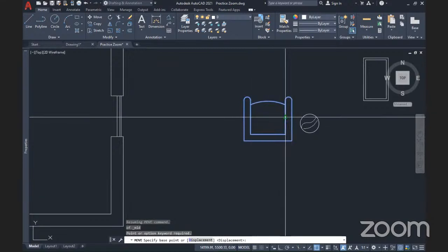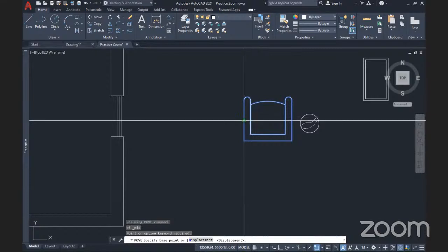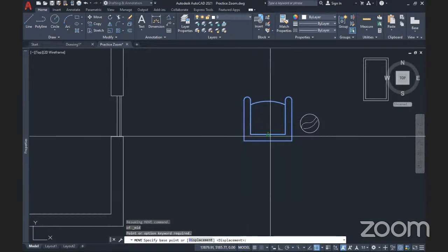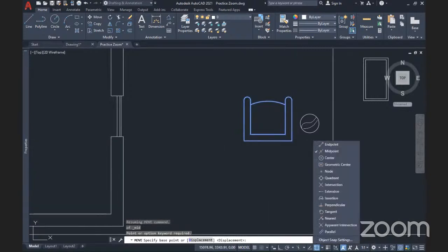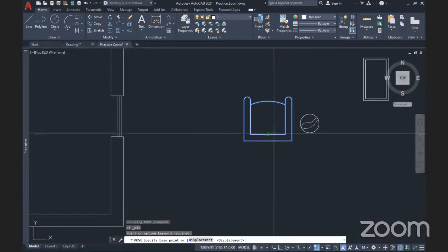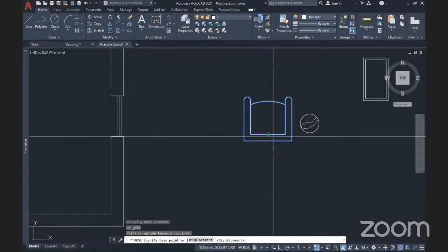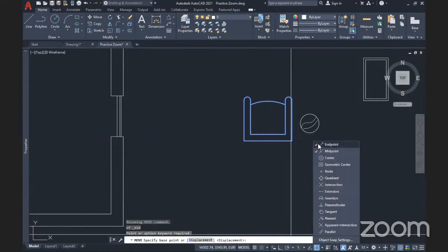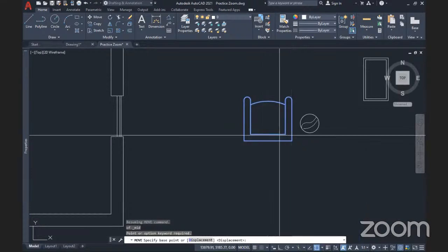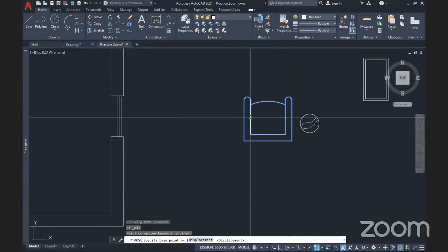It will restrict all my snap to midpoints. The midpoint of each line, it will snap only to the midpoint right now. It won't snap to the endpoint, but to the midpoint, even if I select the endpoint here. See? Oh, wow. That's magic. So this actually overrides the previous command. So we're going to turn it off. So it will select only the midpoints in this case and snap to the midpoint.